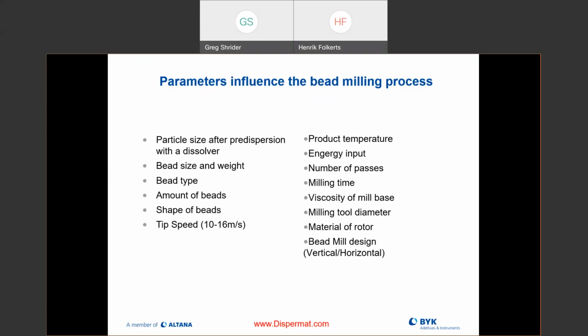It doesn't matter if I'm doing carbon black, I can see a difference, but that's very important when I'm milling light or white products. So always use ceramic-based materials, zirconium, for the milling chamber and milling tool for white products. And then for dark products, stainless steel is fine, or silicon carbide, which is also a ceramic, very, very hard.